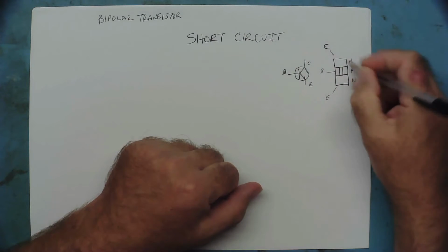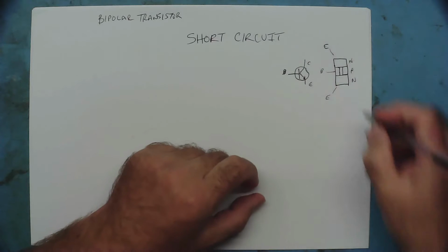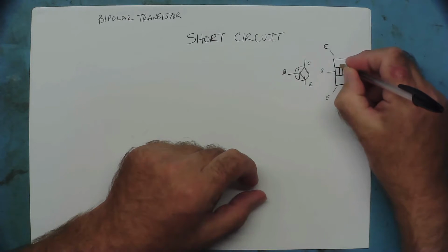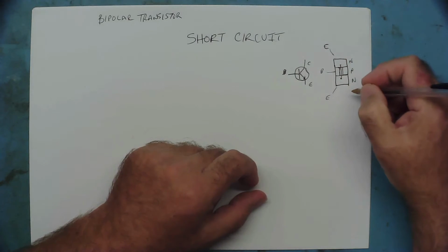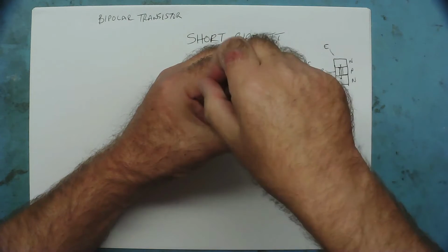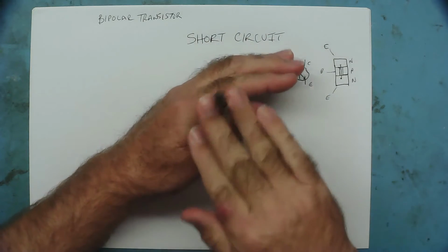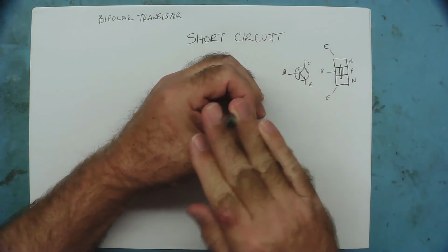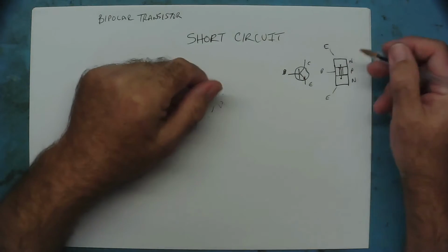So your base, imagine this is circular now. Your base now looks like a donut, with a hole in the middle, and you can get sort of like metallized silicon, if you like, a whisker of metallized silicon that's gone through the hole. So now imagine your base is like a donut and the silicon's blown. I can't hold the pen and show you, but you get the idea, like that. So you can actually have a situation where the collector emitter is short and not to the base.